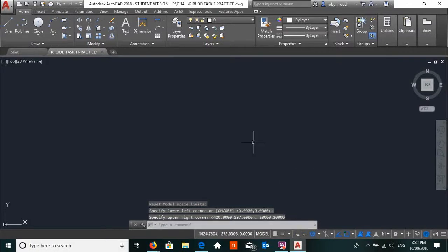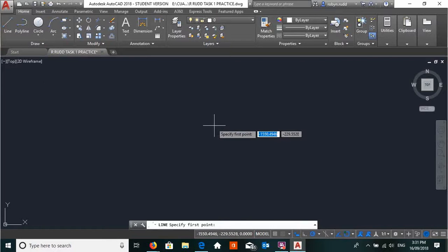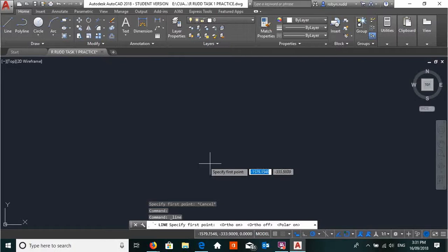So that's given me that. You can see that when I typed it in, I was only typing down here. I actually like my dynamic input on, so then if I'm wanting to choose a line, do you see how the little box appears with the cursor now? When I had it off and I choose the line, there's nothing. So that is what dynamic input does, and I quite like that.